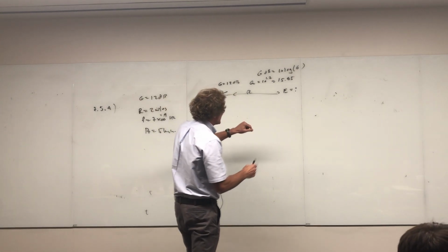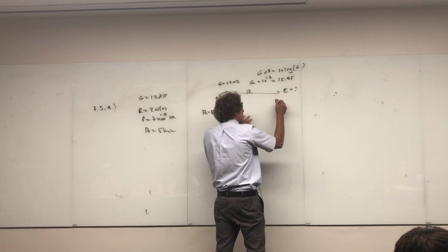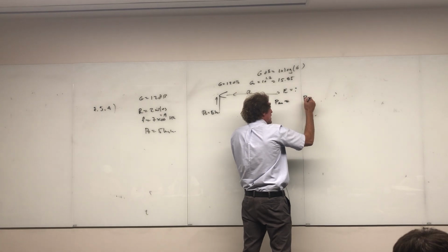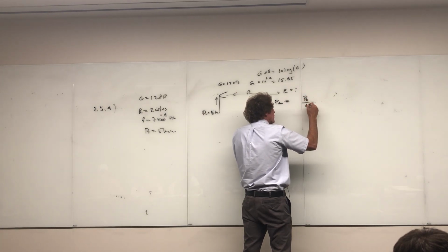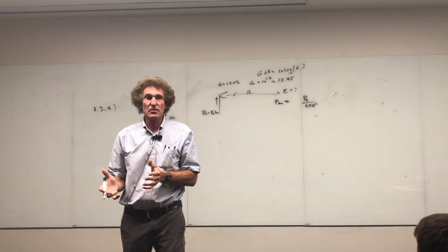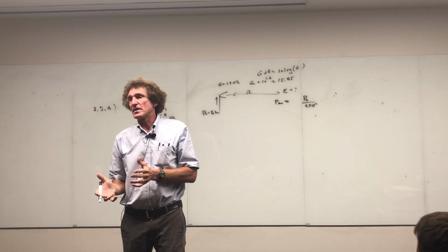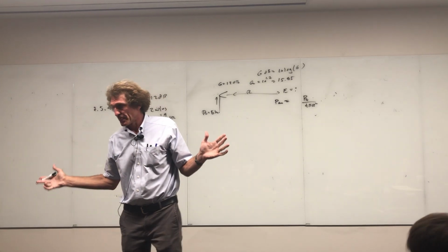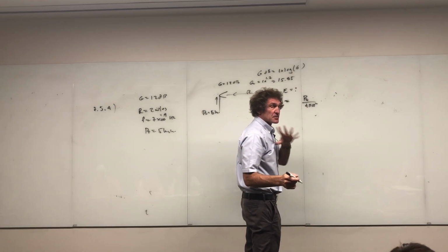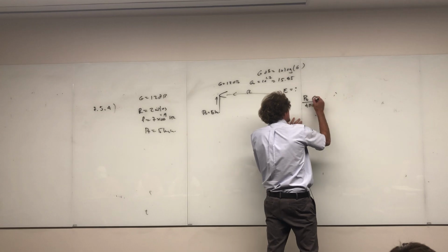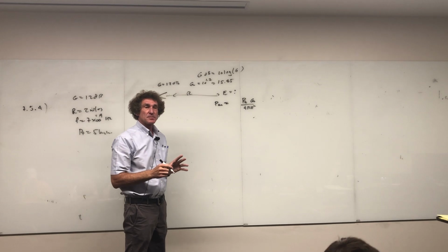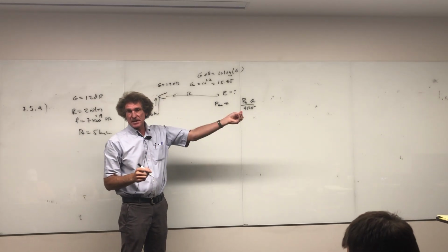We want the E field, but we're not going to get the E field right away. First, we're going to find the average power density out here. And the way you get it is always take the transmitted power divided by 4 pi r squared. Now that's as if it was an isotropic radiator. I keep telling you, think in terms of this. That would be the power density if there was no focusing. We have to still do R in terms of meters, and we'll do that in a second. And then it's times the linear gain. That will give me the average power density. Y'all follow me on this? So that tells me what the power density is out there.